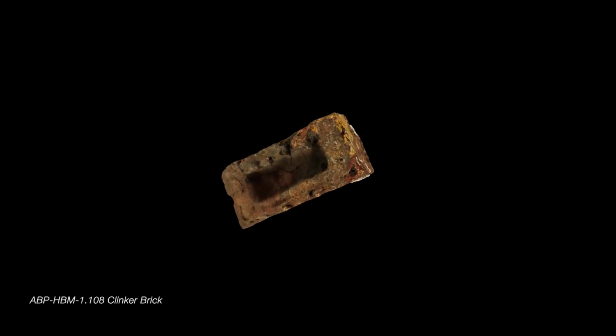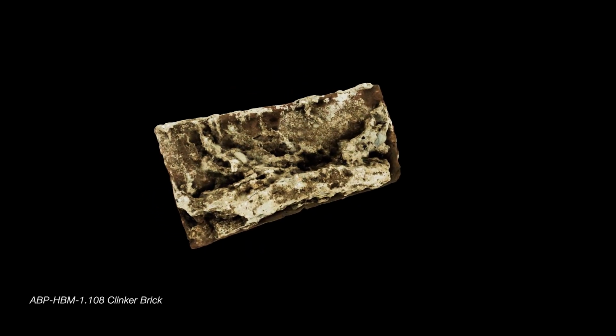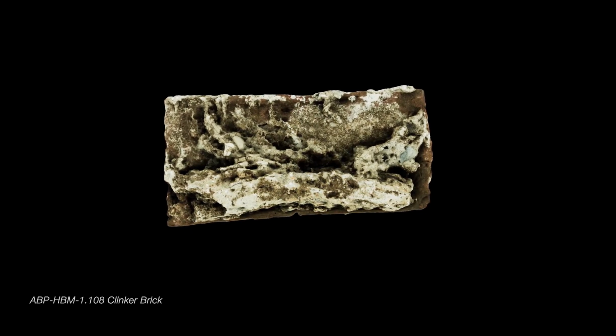So in some of the early examples, we find this mortar from an early brick from Tasmania, and the little bits of shell actually in the mortar show this was burnt from shell lime in those early days. Now, later on, some natural cements were found, which are rather stronger than lime and have some capacity to resist water, say rain and so on.